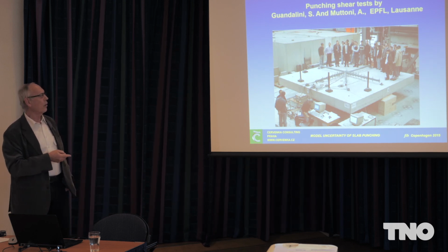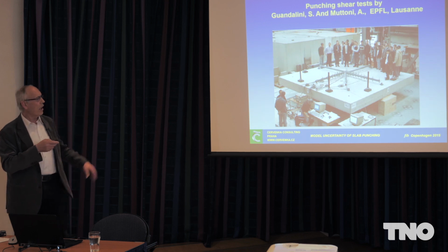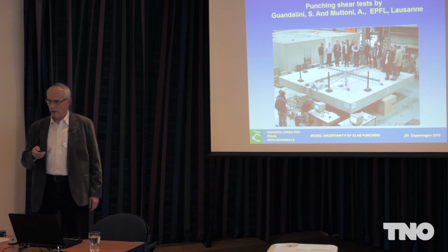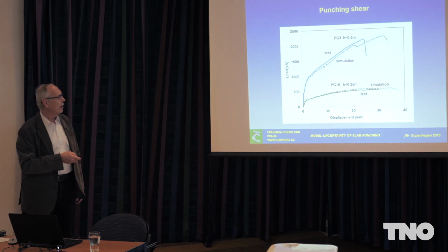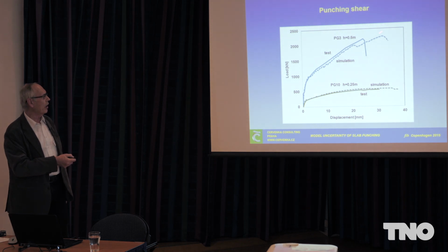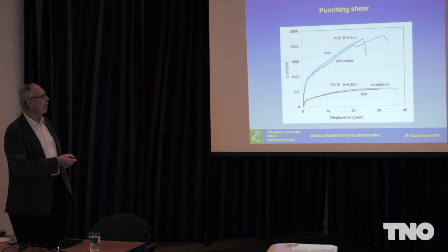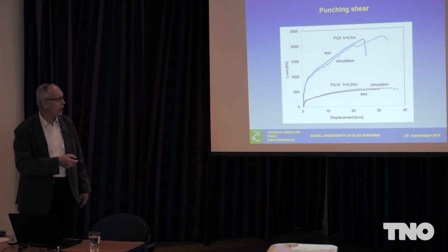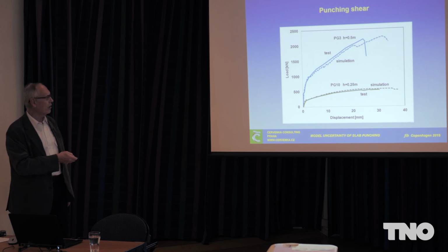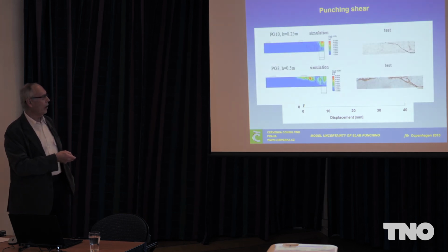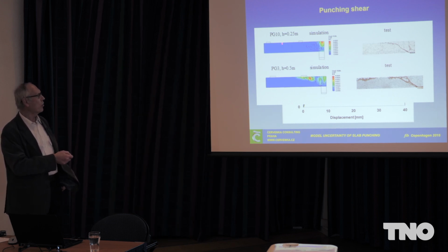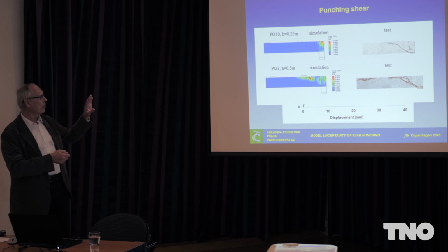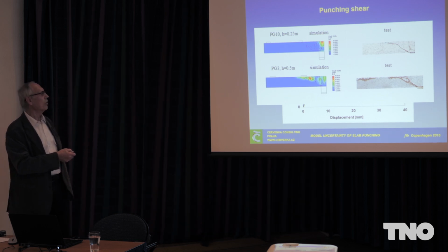This is a test of Aurelio Montoni, different sizes of plates, slabs in punching, without reinforcement. This is the result of simulation. In this case, you can see how it works. We always try to make a simulation which can distinctly show peaks, indicating the resistance. These are the descriptions of failures. In this case, rather coarse mesh. It is not research. It is oriented to design situation, more or less.